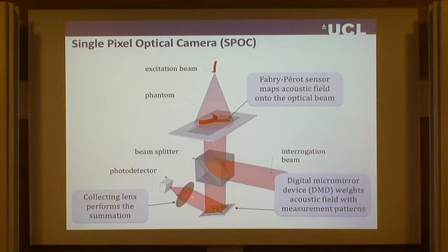So the difference between the Rice camera and our device was that we are using coherent light. Coherent light makes problems with things like DMDs because they act as diffraction gratings. For this reason we had to reverse this. The idea would be to have wide beam illumination on the sensor and then reflect from the DMD, but because of this diffraction grating optic we can't do this, so we actually reflect the pattern off the sensor first. So we had to reverse the idea because of the optic.